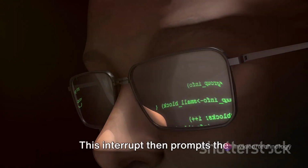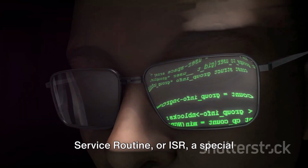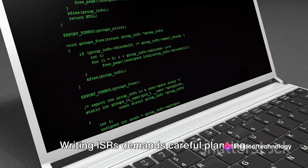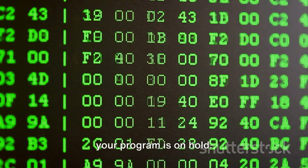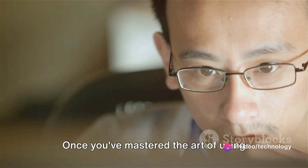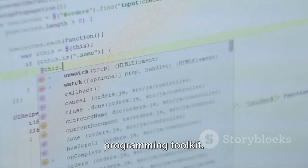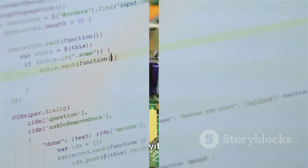This interrupt then prompts the microcontroller to temporarily pause its current task and execute an interrupt service routine, or ISR, a special function written by you, the programmer. Writing ISRs demands careful planning. Your ISR needs to be efficient and quick because while it's running, the rest of your program is on hold. So remember, keep it short and sweet. Once you've mastered the art of using timers and programming ISRs, you've unlocked a powerful tool in your 8051 programming toolkit. With a grasp of timers and interrupts, you're ready for the next step.